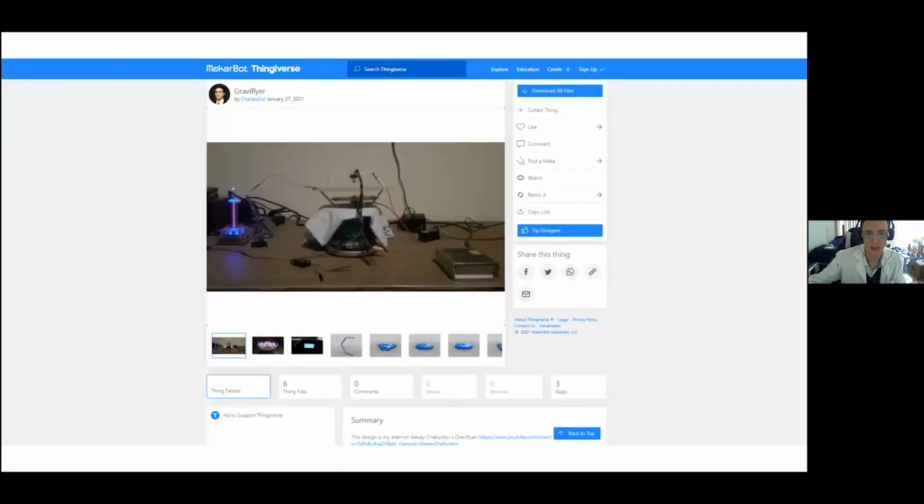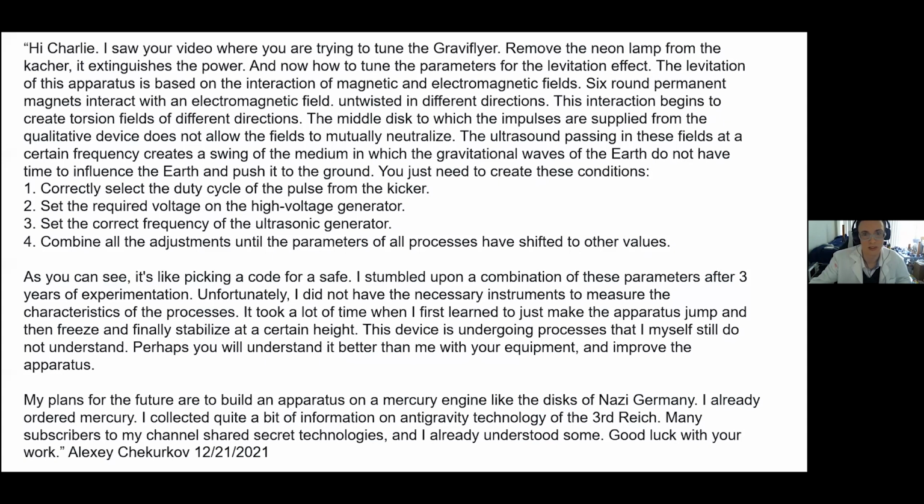All right, again, I have a design on my Thingiverse for the frame, but that's a little older design. I was using the 3-phase brushless motors, which is not a good idea because of the high voltage near those. They use PWM signals to control the speed, and any high voltage or spinning magnetic fields or the AC field from the Tesla coil all interferes with that signal, so it'll randomly speed up or stop and stall if you use that. So I recommend using the fan blades he's shown.